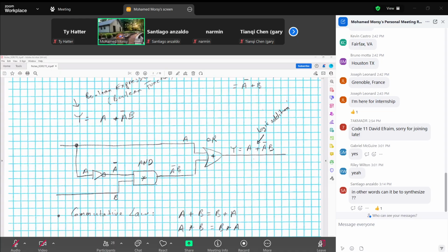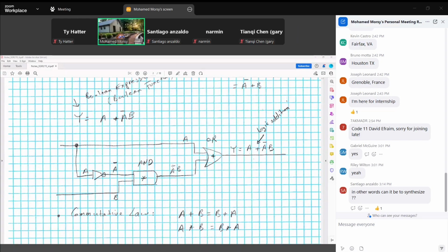So this AND gate has two inputs. One input is A inverted. It's very systematic, you know. I mean, it solves itself by itself. It's easy. And the other input is B. Now B is the minimum variable we can get. Now look at A inverted. When we have A inverted, this means it came from where? What is the gate connected here before A inverted? A NOT gate? NOT gate, perfect, or inverter.